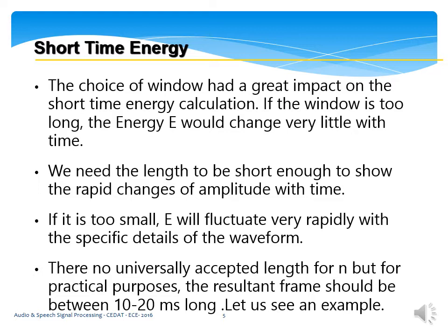There is no universally accepted length for the number of samples that you should take inside this window. However, for practical purposes, we want the frame to be between 10 and 20 milliseconds. Okay, let us look at an example.